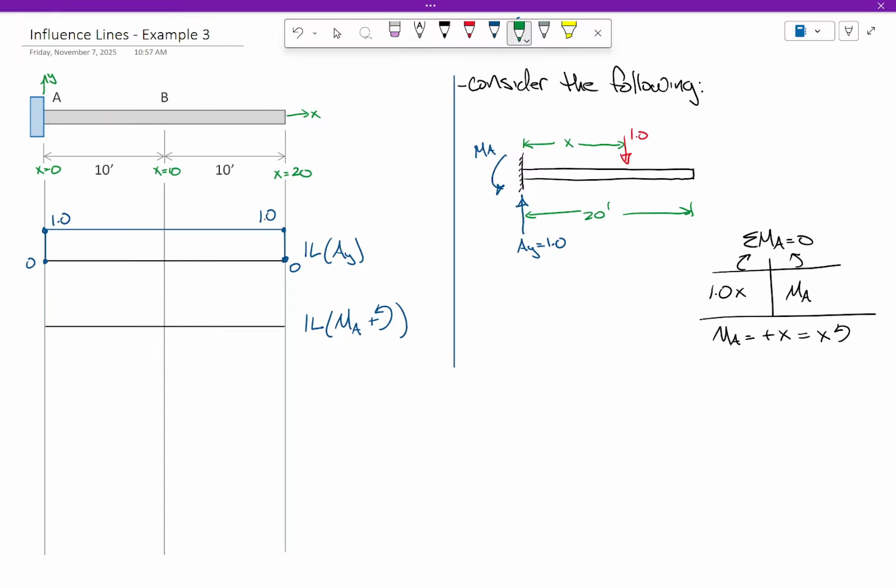A linear line. What's that? A linear line. Okay, so tell me what it is here. 0. What is it here? 20. 20. So, this, exactly right. So this, that's the influence line for the moment reaction at A. Does that comport with the Mueller-Breslau reaction?